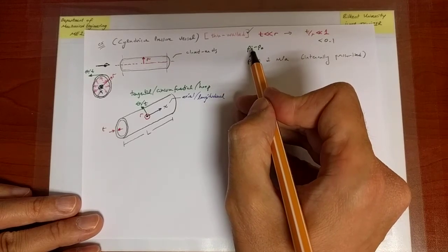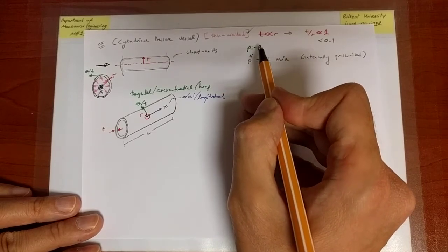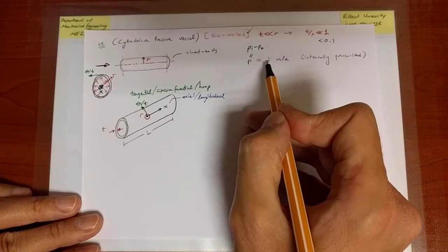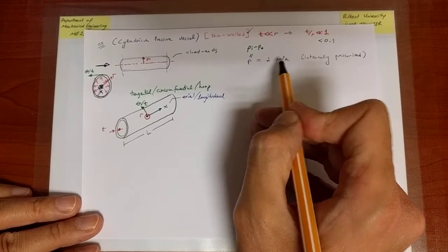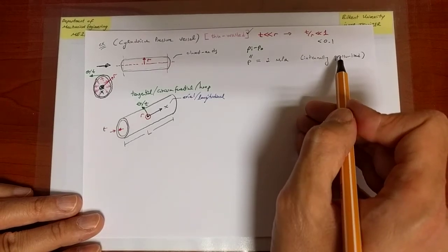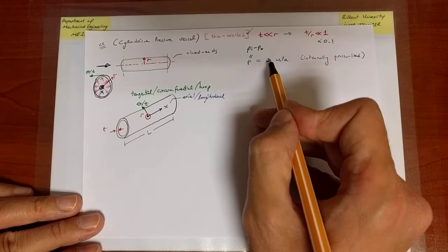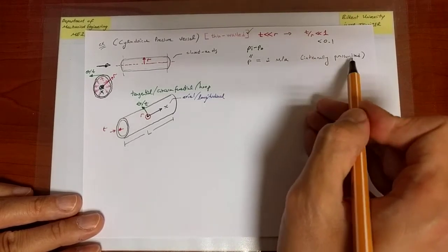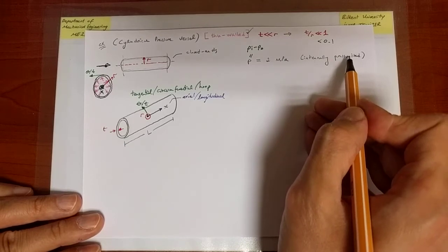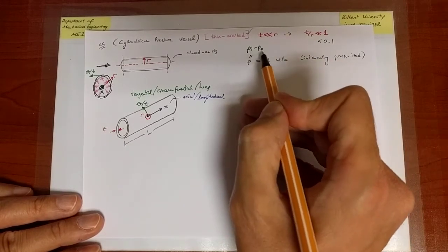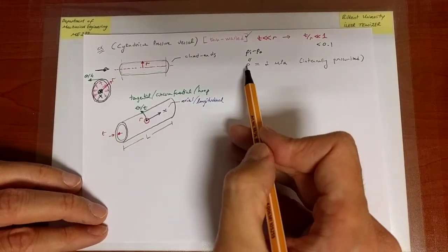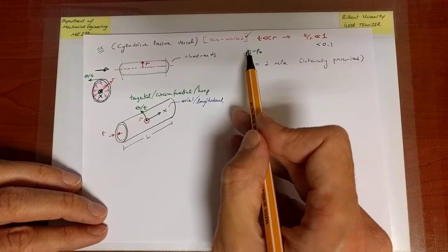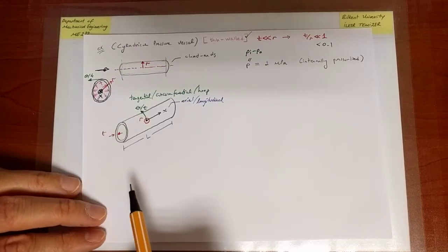If the internal pressure is less than the outer pressure, then the difference P would be negative, and we would call it minus 2 MPa internally pressurized. That would be strange. Instead, we would say P equals 2 MPa externally pressurized, in which case it would stand for PO minus PI instead of that minus that, right? So ultimately, this P value that we are writing here indicates essentially the difference between the inner and the outer pressures.